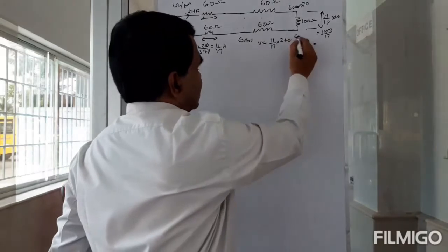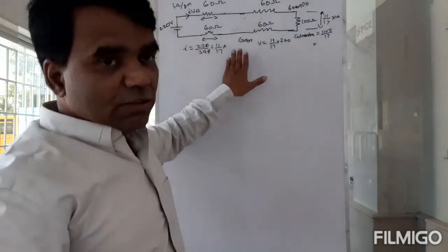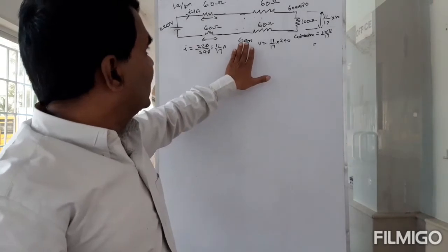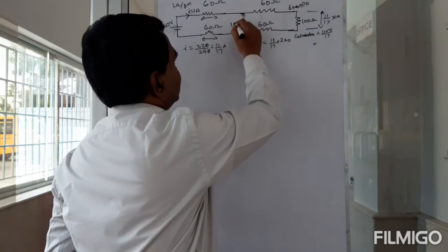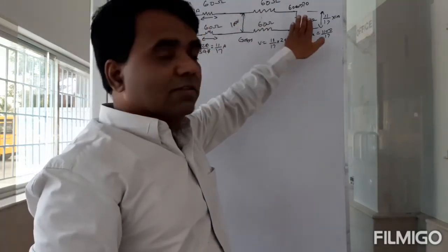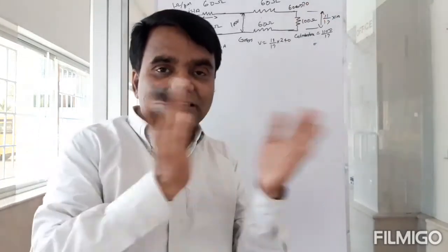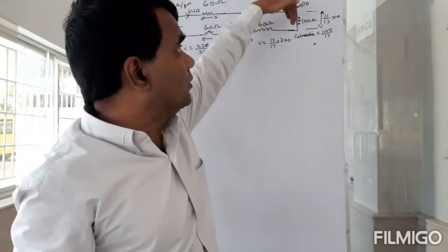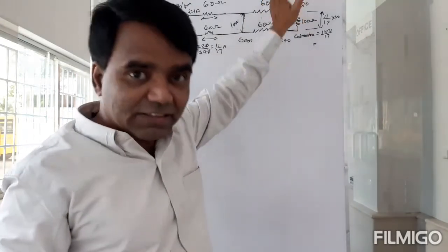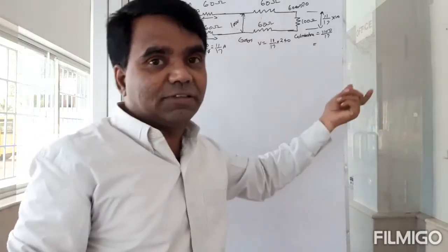That was in Coimbatore. If your house was in Gobi, then you were getting 100 volts here. And if your house is in Coimbatore, then you are getting about 60 to 70 volts. You see, it's coming down. So the current you can draw is also coming down. So the power you can draw, V into I, is coming down for you. So you can draw only less power from there.